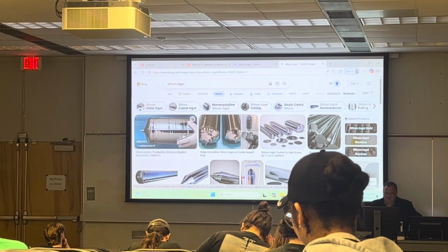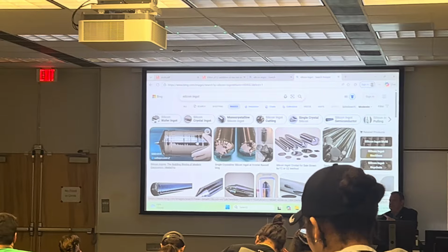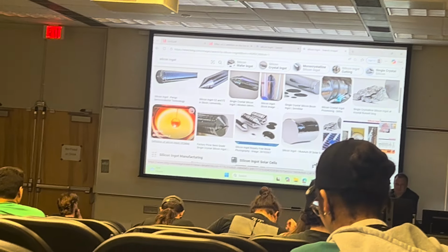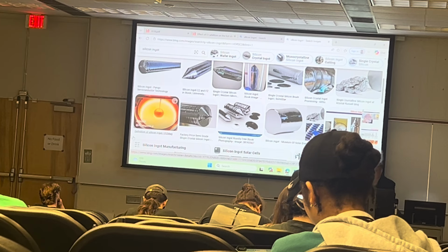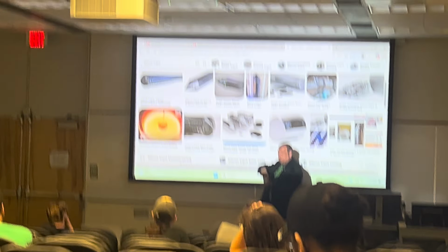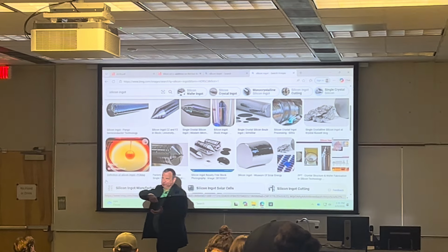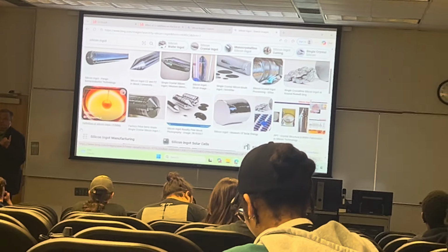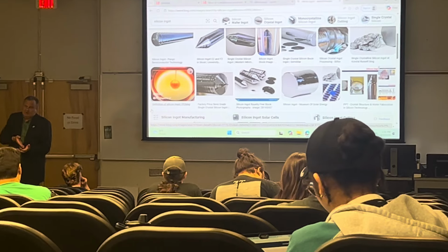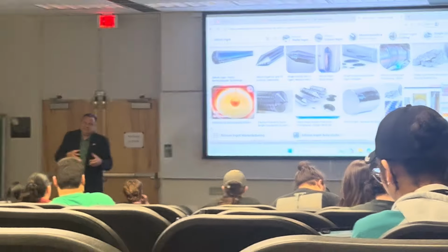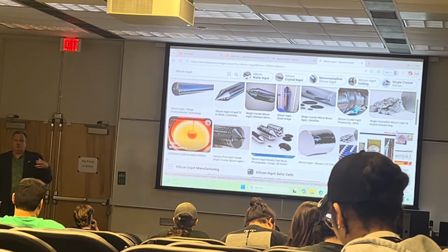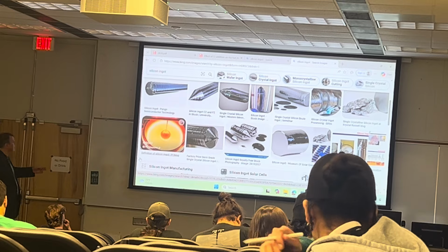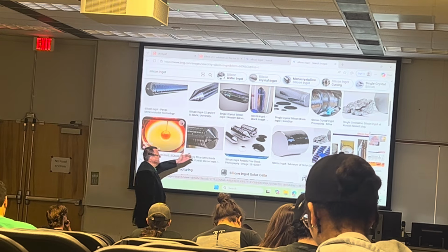You can see a human hand, so you know. And lengthwise, this is the actual growth process, where it is very slowly pulled from a liquid solution. There's very high temperature, very precise temperature control, and a very slow rate at which you're pulling it out, so that the atoms have enough time to arrange in a single crystal. And then after you get this ingot, it is sliced.